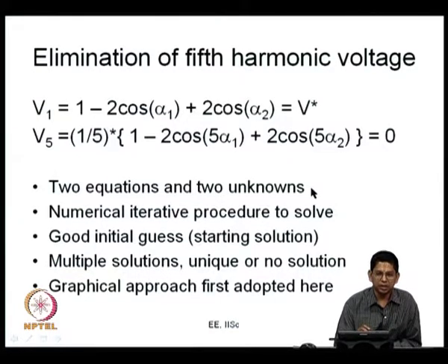As I mentioned in the last lecture, the fifth harmonic is the lowest harmonic, and that is what faces the lowest amount of leakage reactance among the harmonic voltages. The seventh harmonic will face much higher than that. The harmonic voltages see the machine as its leakage inductance.